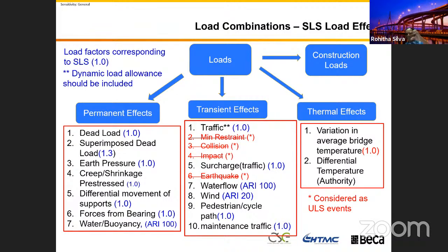Originally you might have 50 mm or 75 mm, 80 mm asphalt on top. When it wears off and the bridge deforms, you come back and overlay again to make the surface smooth, so your thickness may be 120 in some places and 50 in others, uneven. Because there's a risk, they increase by 1.3.